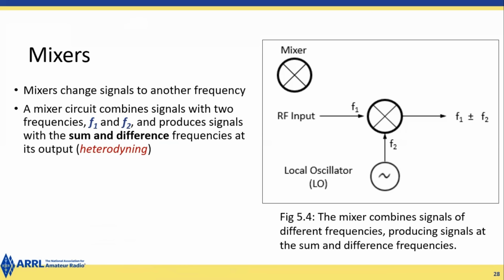Amplitude modulation. There are three types of AM signals. Full AM has both the sidebands and the carrier. The carrier is represented by the vertical line in the middle of the sidebands over here. And the sidebands can contain speech or data, and the signals have been used to